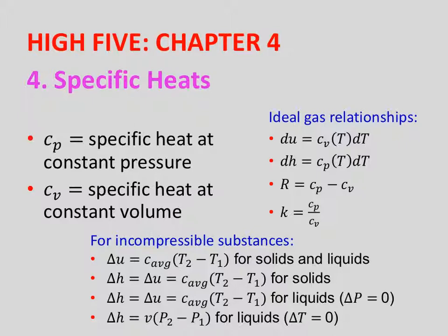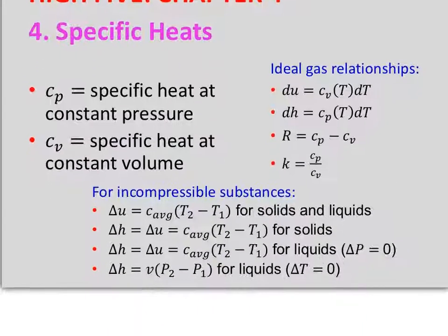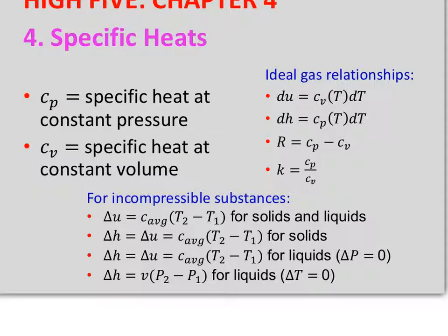For incompressible substances, change in U equals C average times T2 minus T1 for solids and liquids. Then change in H is change in U, C average times T2 minus T1 for solids.